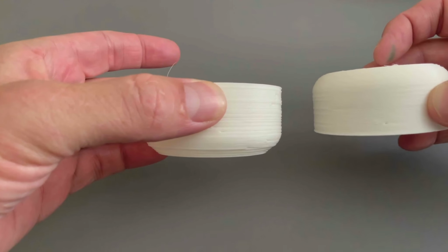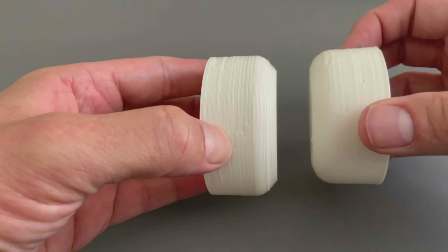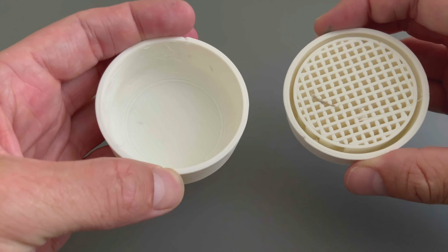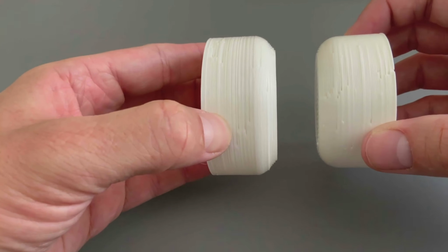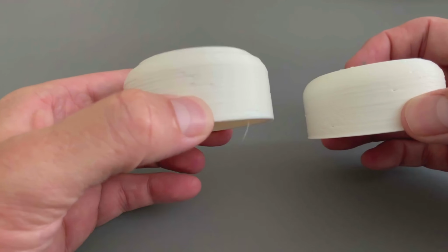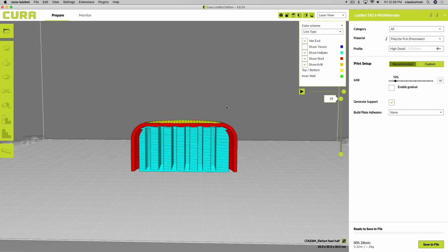This is the print orientation. And there you can see the outcome. But also the left one is faster. The right one is slower because of the added support. But the right one simply looks better. Also, everything was printed horizontally, so I have nice horizontal lines for these rounded edges. Okay.